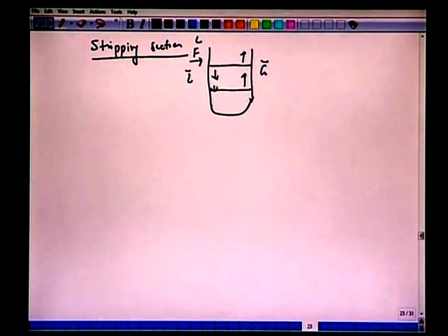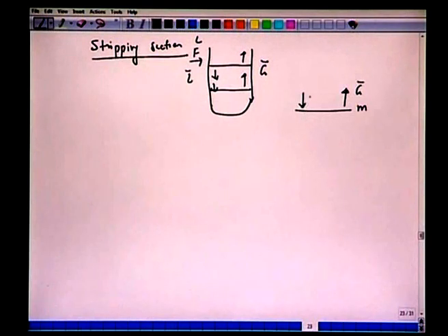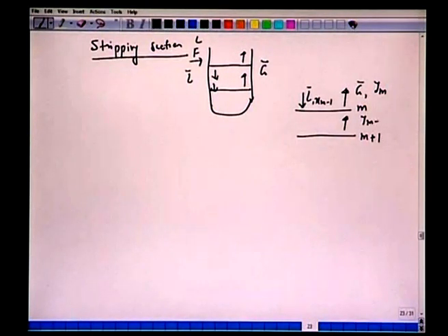Alright, so we can do the same thing. We can choose a plate m. The vapor leaving is G bar. Liquid arriving here is L bar. The mole fraction will be ym. The mole fraction will be xm minus 1. We have m plus 1. This vapor is ym plus 1. This liquid is xm, with the same molar flow rate, no suffix here, G bar.